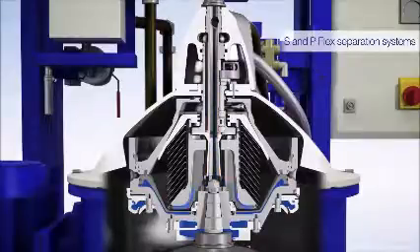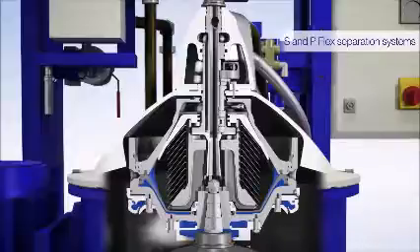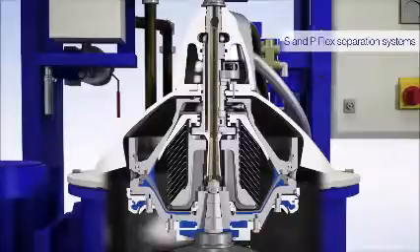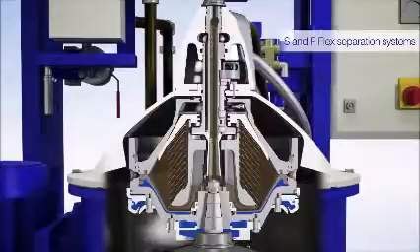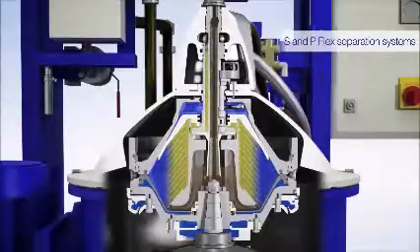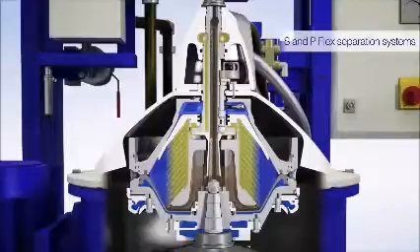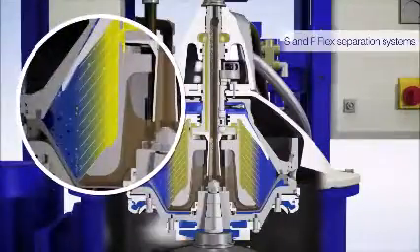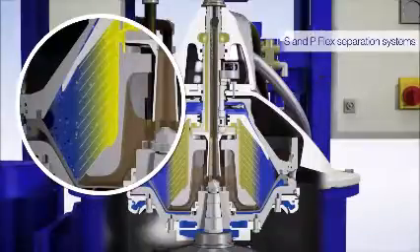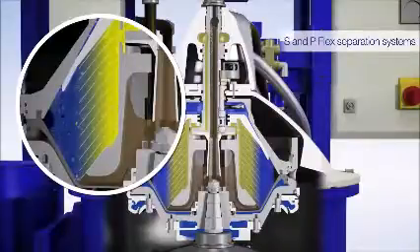For example, water is separated from oil because water and oil are immiscible, which means they are incapable of being mixed. Also, there must be a difference in the specific gravities of the materials before they can be separated by centrifugal force. When a mixture of oil, water, and sediment stands undisturbed, gravity tends to form an upper layer of oil, an intermediate layer of water, and a lower layer of sediment.